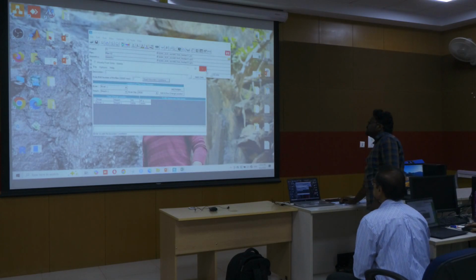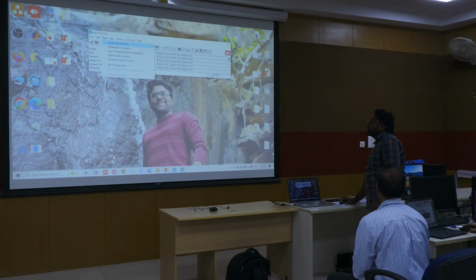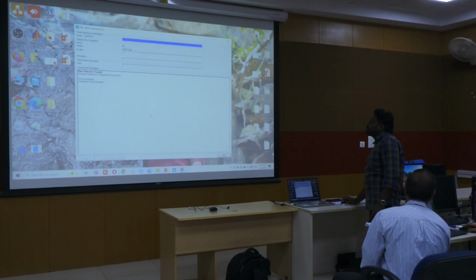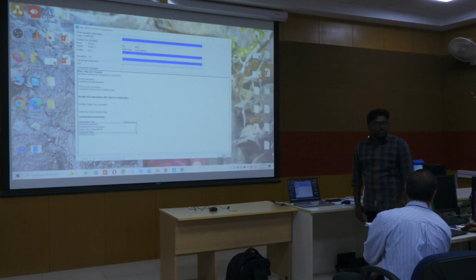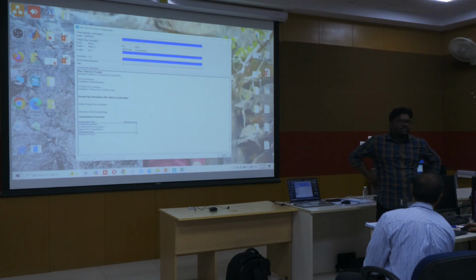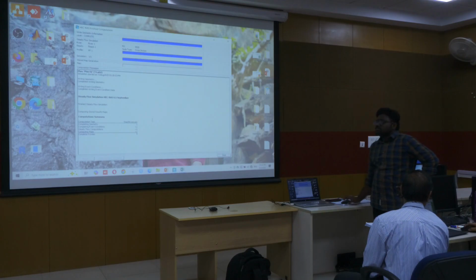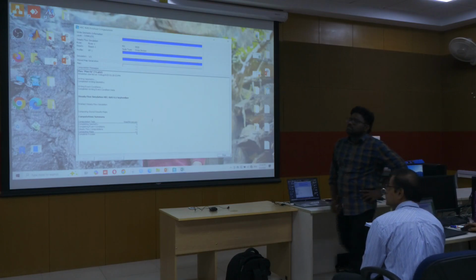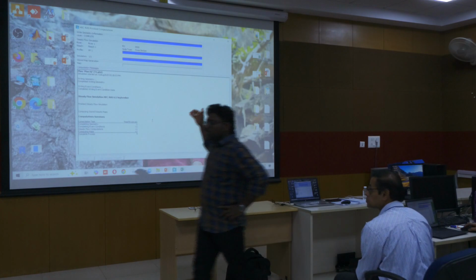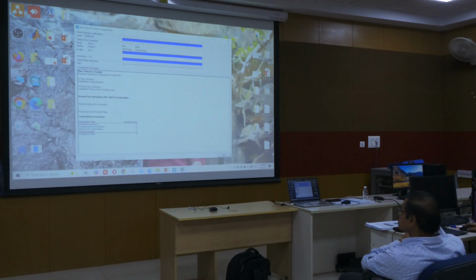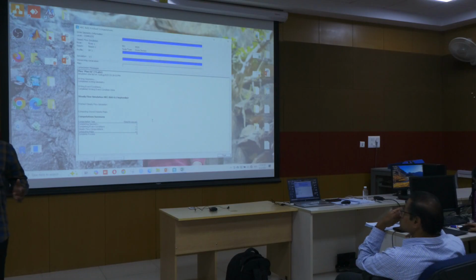Let's see. Go to run, steady flow analysis. Click on compute. It will run. Okay. So for the same flow, yeah, it is subcritical flow. Why? Because it is a gradually varied flow, so the water is not suddenly changing.